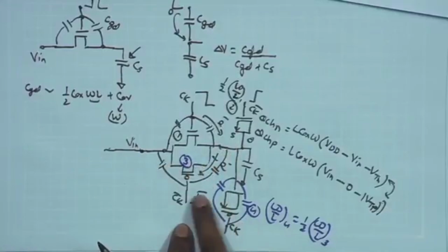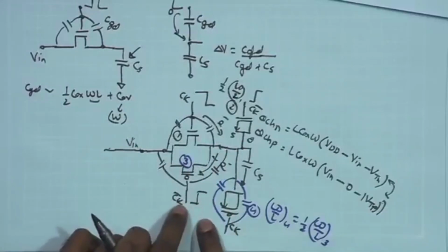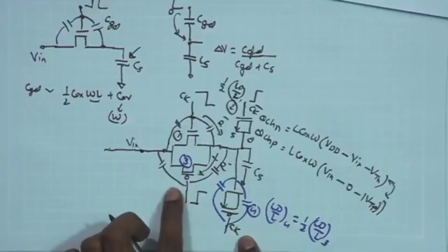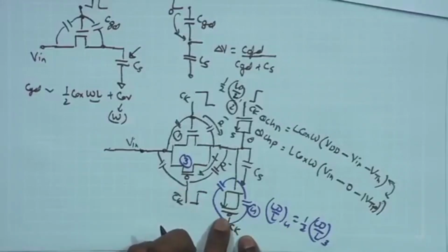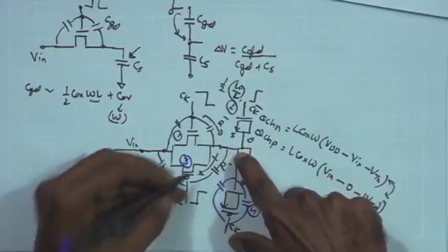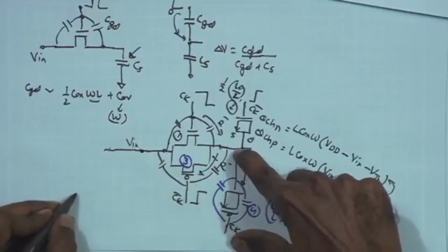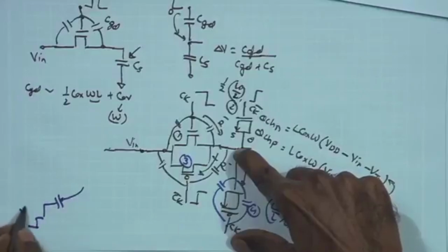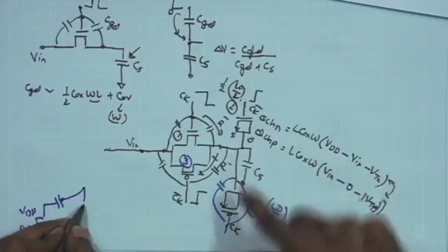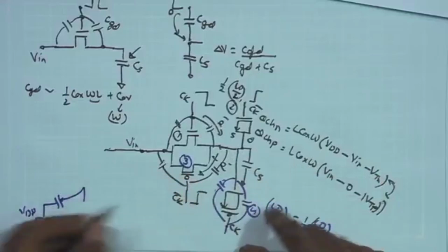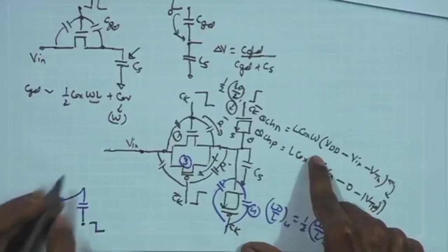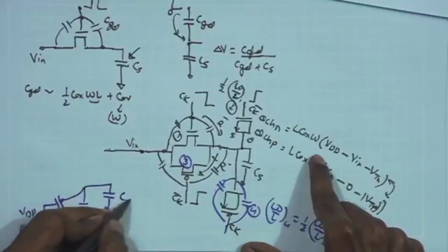and as a result if I look at the condition, I have clock transiting from 0 to high over here, but here you have just opposite transition, you are applying the reverse clock over here, and as a result if I look at the total signal over here, at this node I can model it as the first capacitance having a transition from 0 to VDD, and the second capacitance, total capacitance provided by the MOSFET over here, which is having transition from VDD to ground, and then I am having the total capacitance over here CS.